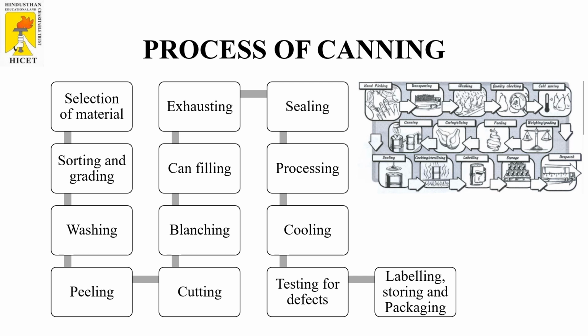Next, coming to the peeling process, it includes the peeling, coring and pitting process, where the peeling can be done using mechanical or knife peeling, or peeling by hand, abrasive peeling, flame peeling, or peeling by heat or hot water, flash steam peeling, or lye peeling. All these types of peeling can be used in order to peel the fruits or vegetables. And next, coming to the cutting, halving or slicing process.